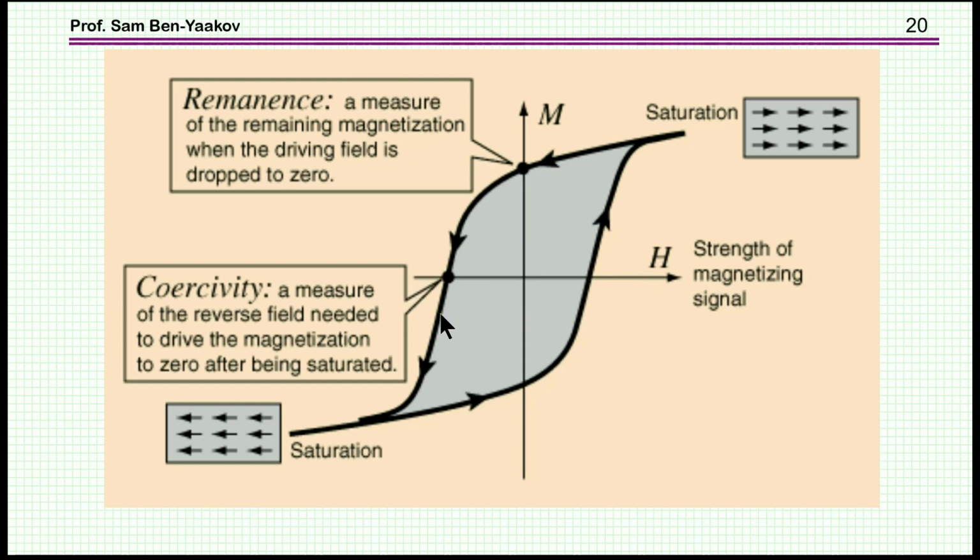And then on the other hand, there's the coercive magnitude of current or field that you need in order to bring the magnetic flux back to zero. So this is an error. This is a zero error. And therefore, you would like to have a unit built with a magnetic material that has this very narrow and this value here as low as possible.